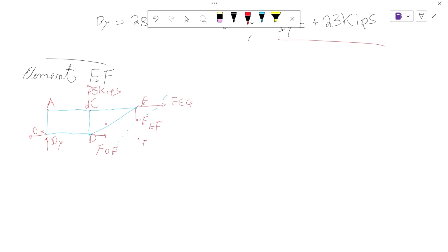All right, so first of all, we only care about this force, so we don't have to do a lot of work. We only have to care about the summation of forces in Y. So summation of forces in Y equals 0 to keep it in static equilibrium. And in that case, we know that this is going to be By, sorry, Jy, which one do we have to do?